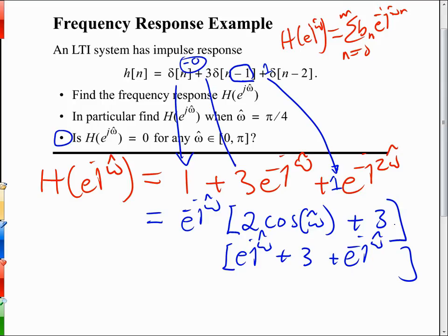The trick is trying to get two equal and opposite signed complex exponentials. So an e to the plus j and e to the minus j, because we know those can be stuck together to form a cosine. Because you'd have to put a 2 inside of each of these to make them into a cosine, we have to put a 2 on the top to balance that off, and that's how the 2 gets pulled out in front. So then in the factoring we're left with that stuff that I just circled in green, which forms the cosine.